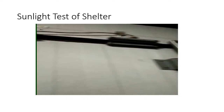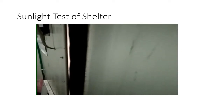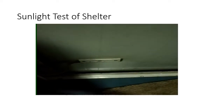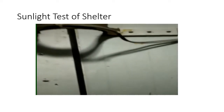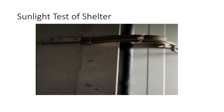We are seeing all across the door, and we see that on the top side there is no leakage, but on the left hand side also we can see that this is a place where a gap is there. Again we are closing the door, and again we are re-verifying, and we are seeing the gap at the same place, and we need to correct the gasket.